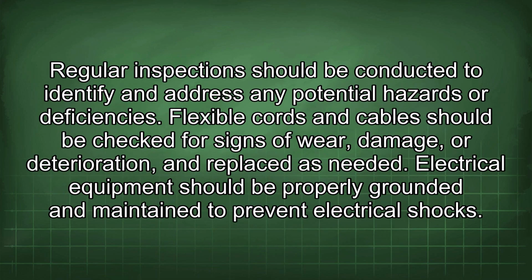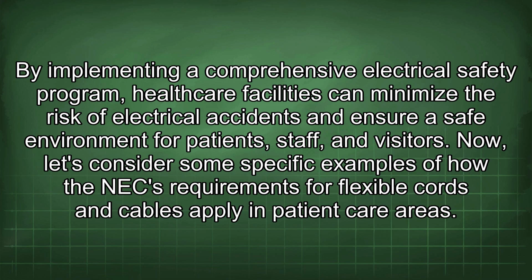Regular inspections should be conducted to identify and address any potential hazards or deficiencies. Flexible cords and cables should be checked for signs of wear, damage, or deterioration, and replaced as needed. Electrical equipment should be properly grounded and maintained to prevent electrical shocks. By implementing a comprehensive electrical safety program, healthcare facilities can minimize the risk of electrical accidents and ensure a safe environment for patients, staff, and visitors.